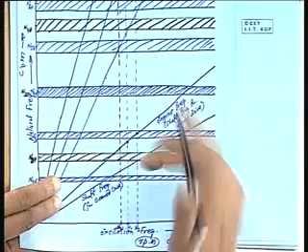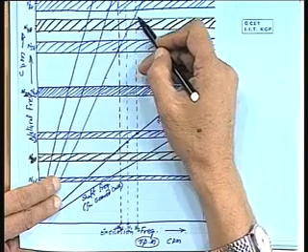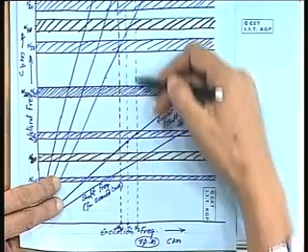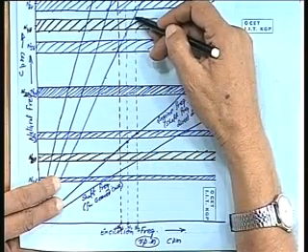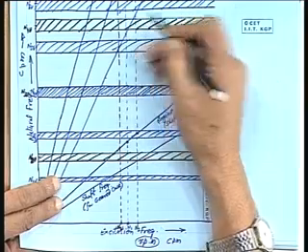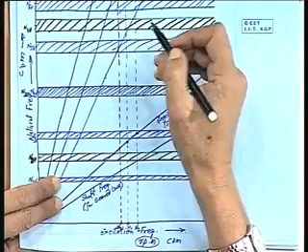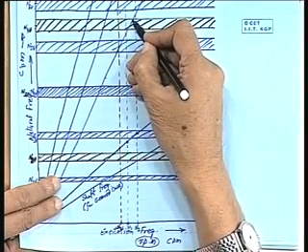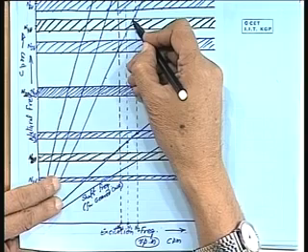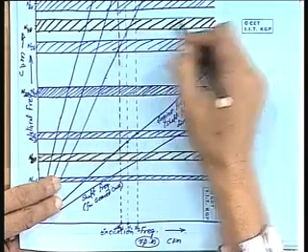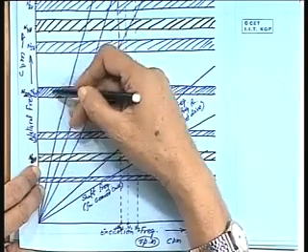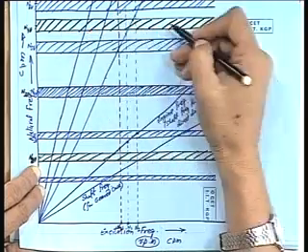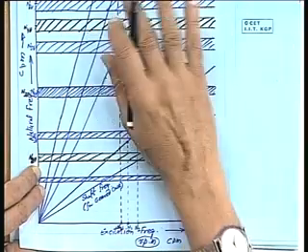Okay? Say for example, if this engine by any chance was selected for a 3 bladed propeller and there is a drop in power, then this frequency will come down straight away here and try to excite this frequency here, which is one of the primary modes, 1st, 2nd, 3rd mode of horizontal vibration, and the ship will always vibrate.